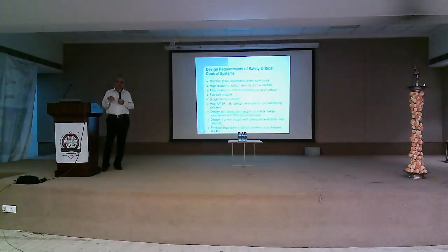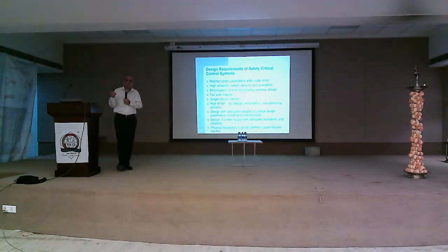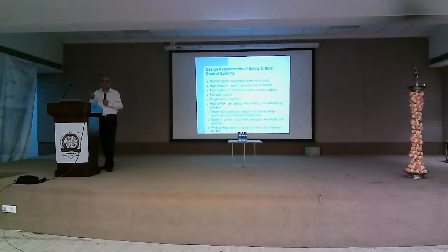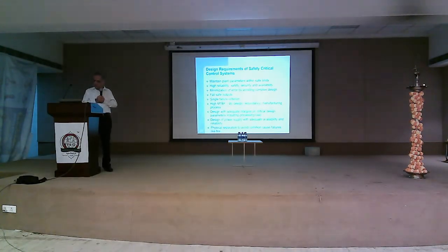Now if the system fails, we can keep the valve as it is in the last condition. So our system is designed in that way. Like, if it is fully closed, it will remain in that condition. You have to design it. High MTBF is assured by design redundancy.